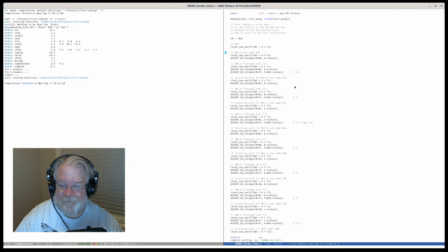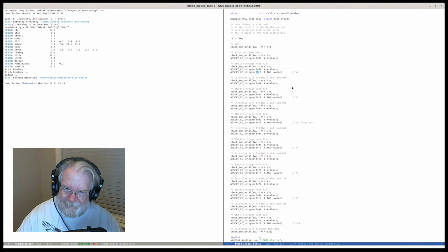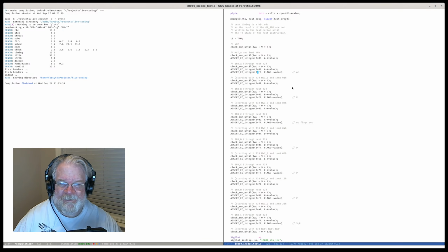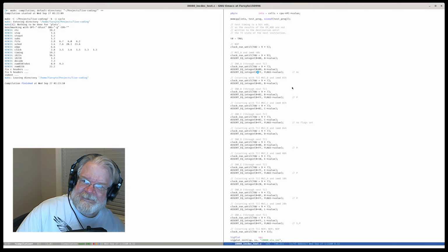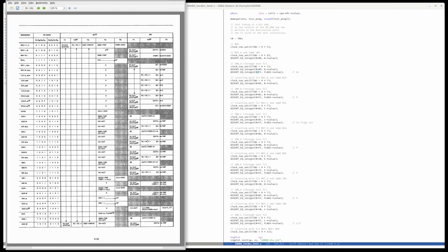But before I can say the test is passing, I need to check this by eye. Now, you'll notice that all the flag values were set to FF, which means remember we set our flags to the high impedance state when we come out of reset, which means our flags have no defined value. Let's take a look at what the documentation says about INR affecting the flags.